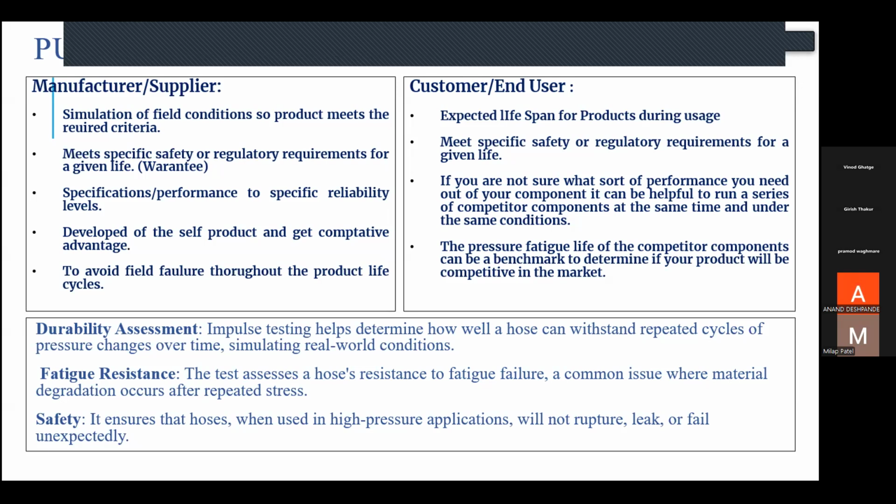So the fatigue failure of the hoses is the main cause which triggers the degradation of the hoses. And when repeated pressure impulsation goes into the hoses, it starts imparting into the hose material or joints, and then fatigue starts. So initially maybe the hose looks very good during the initial testing, like proof pressure testing or pull out testing kind of thing. But when impulsation actually starts, it will give us the correct criteria by which you can define that the hose can perform to this much of fatigue life, and that is the main concern for the safety of the system or safety of the hoses. So that is very essential, that how impulsation behavior of the hoses or overall tube assemblies is to be defined.